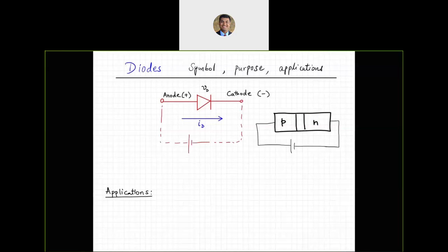So they are going to move this way, away from the depletion layer, thereby increasing the depletion layer, and now the charge cannot go from P to N. So we will not be able to get the flow of current in that case.